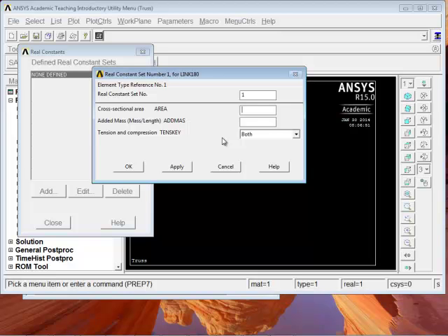8 inches squared. So we're going to put an 8. But notice what it doesn't have. We put an 8, but it doesn't say units. So we need to be very, very careful with units here. You need to be consistent in your own head because this is very generic, but then you have to be careful with units on your own. It's not going to spell them out for you. So we got 8, and now we know that we're going to be using inches from here on out. So anywhere we see feet on this diagram, we have to convert that over.